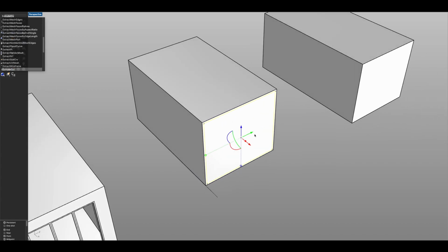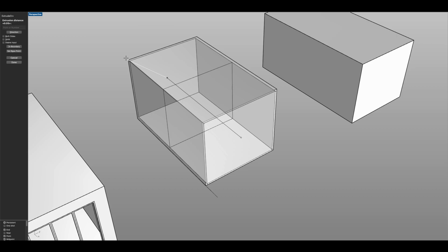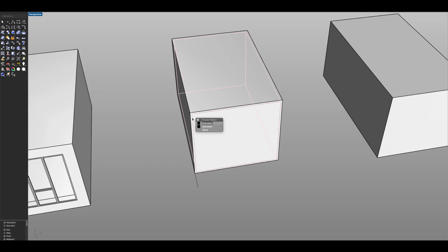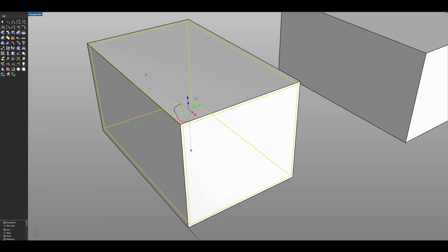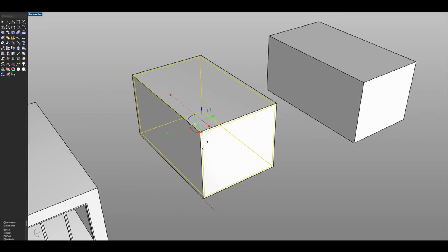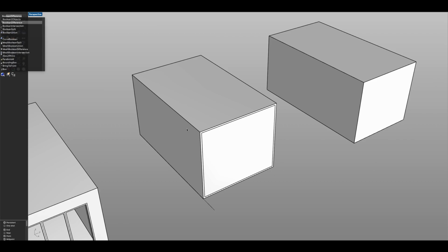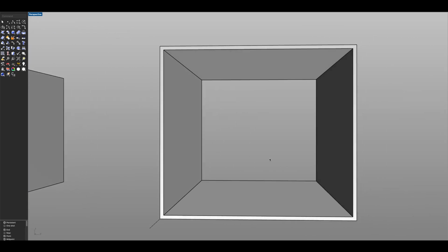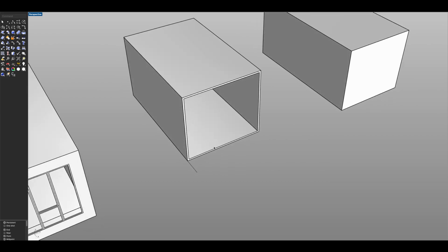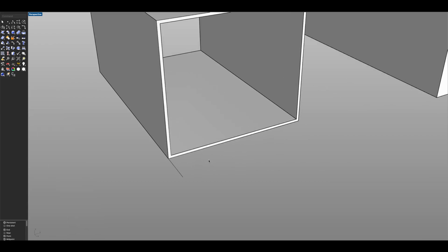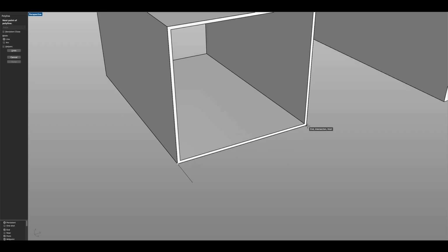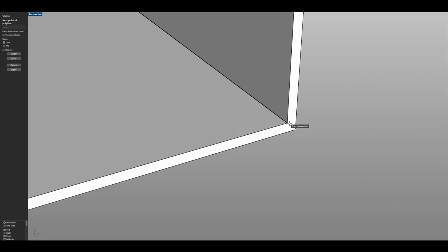Now I'm going to make an extrude curve on this one all the way to the back, like that. Okay, we can delete this curve now. Now we need to select the inner extrusion and go for a cap, like so. And now we simply repeat our Boolean process as we did before to get a nice, clean, and open room here.